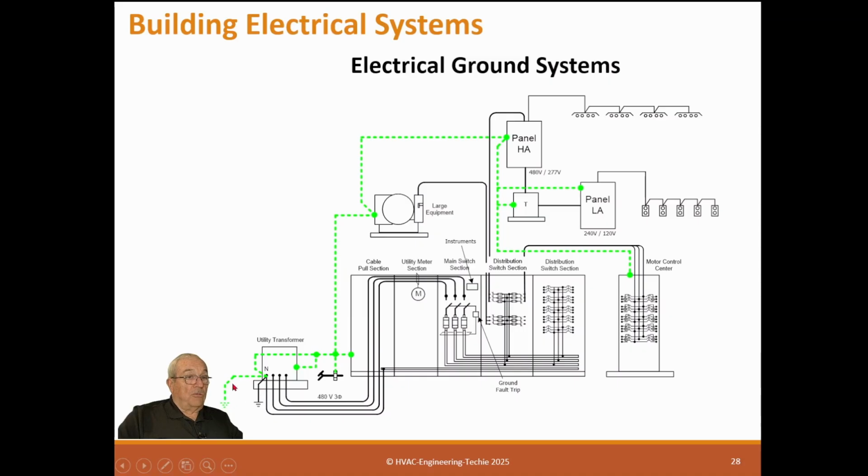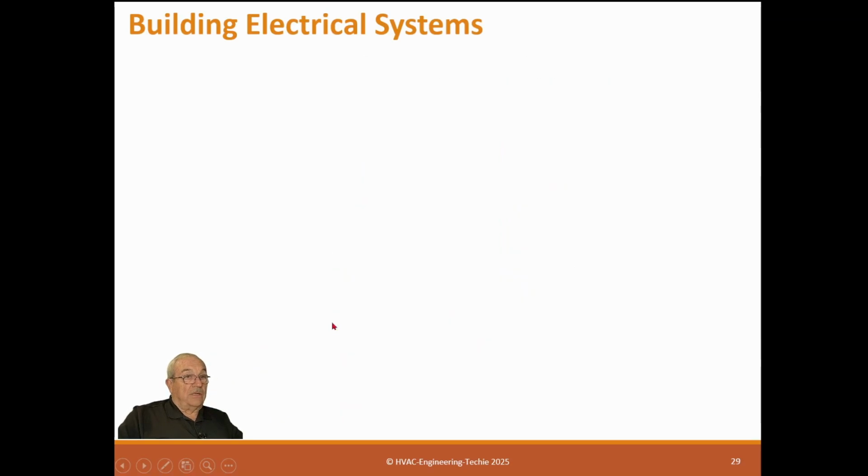So basically we normally have a continuous ground system between all major components and panels and transformers. Normally they have that way, but especially transformers. And this continuous bond cannot be a bolted connection. It needs to be a welded connection or a crimp bond. It can't be bolted. So that's the only thing you kind of watch for on major ground systems: that it is a continuous ground.